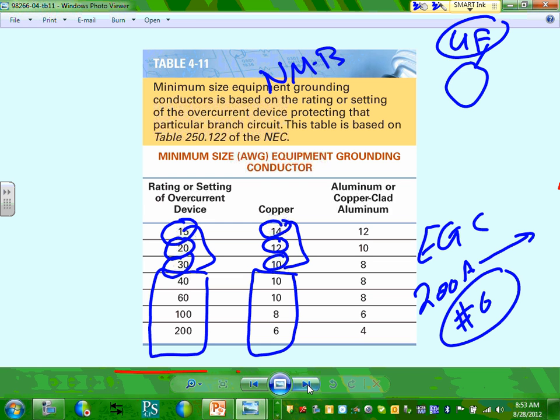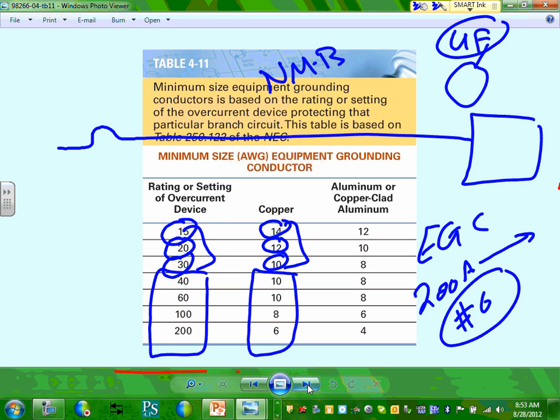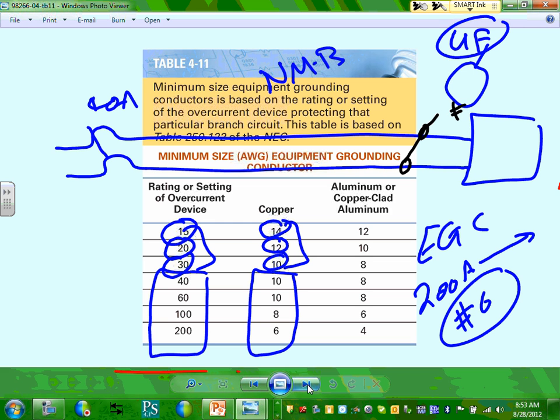Example. So if I have a machine here, and I'm going to tie this machine 240. Okay, this is a 40 amp machine. Here's my conductor. For a 40 amp machine, what do I need? These have to be number 8, right? From the code, 2 conductors, number 8. Now I need to pull a ground with it. Here's my ground. It's no hots. So what do you guys think the ground is going to be?